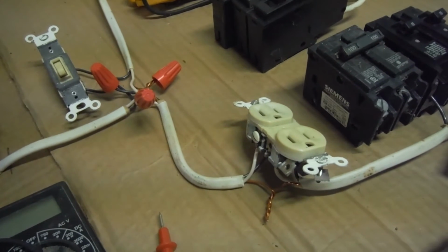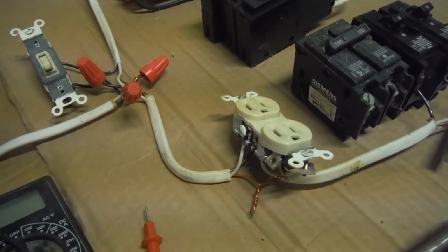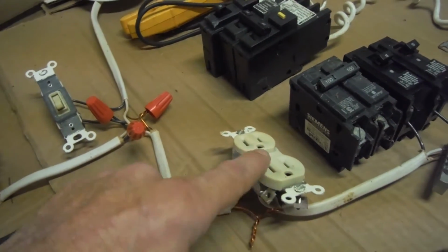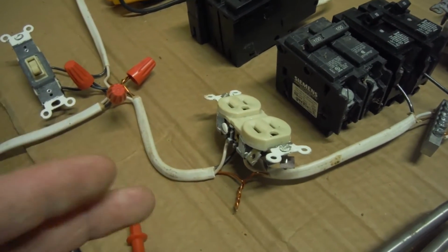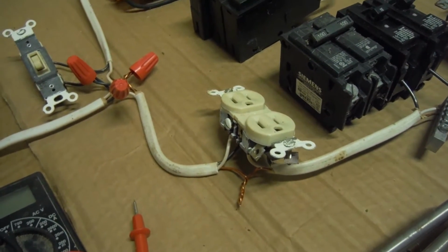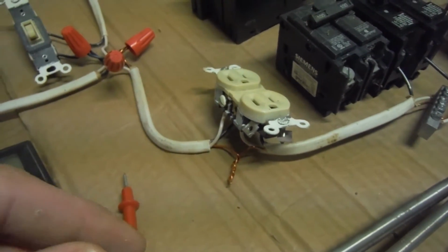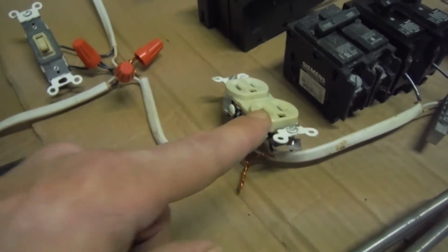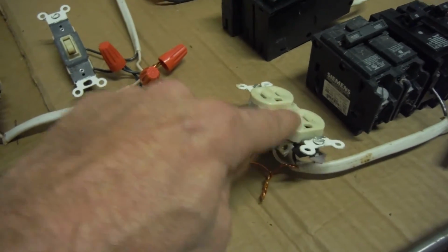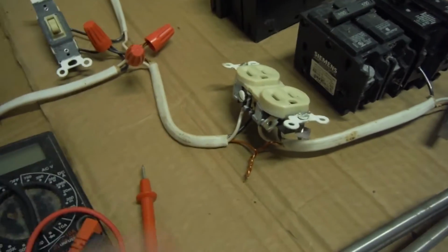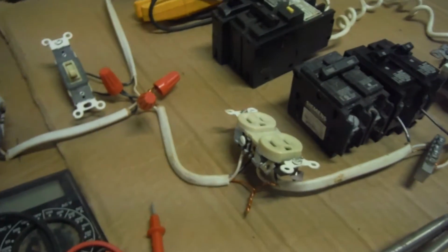Quick troubleshooting tip, if you suspect that's one of the things, you can very, very gently tap these outlets with your foot, with a rubber sole, and be gentle with the impact. If that is the problem, usually your electricity will come back on or off just because it's being jiggled. You usually know that it's pushed in on the back there instead of screwed in. And like I said, I recommend screwing it in.